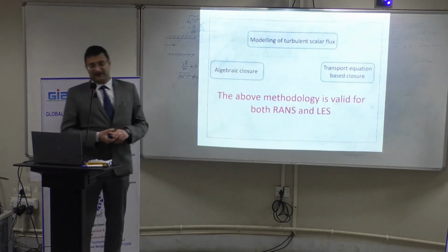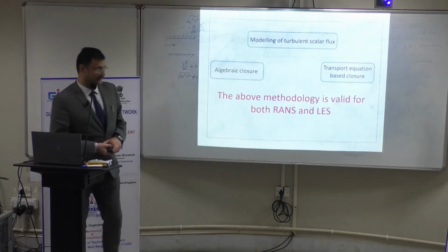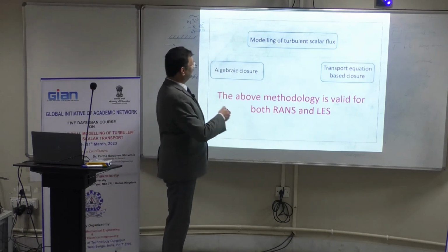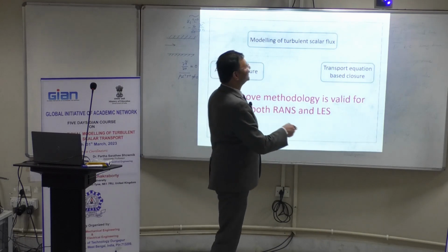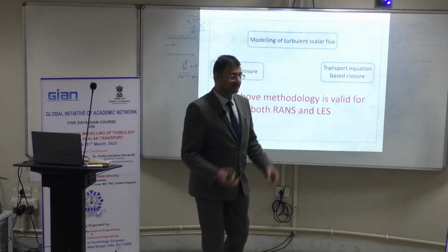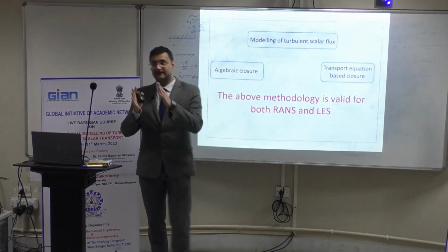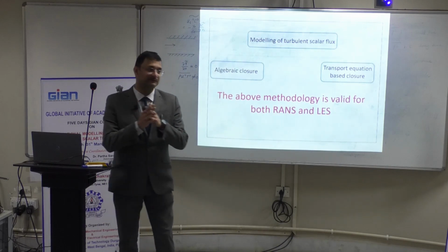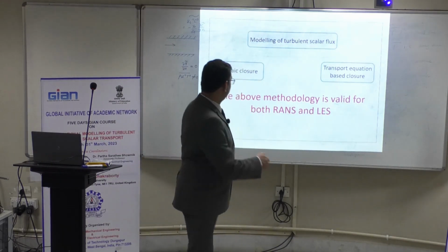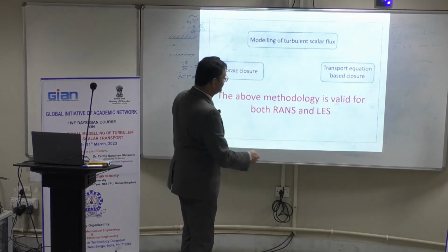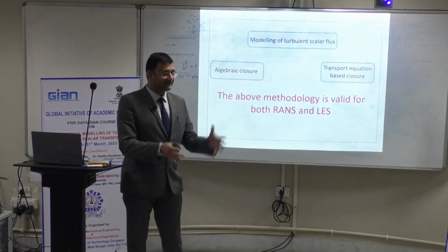Modeling of turbulent scalar flux. You have the option of algebraic closure or transport equation based closure. It's basically the same logic that we talked about when we talked about the Reynolds stress closure. Okay? And the same methodology is also valid for both RANS and LES.